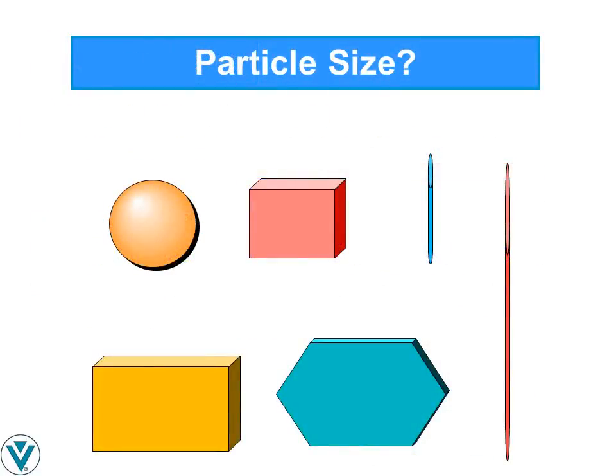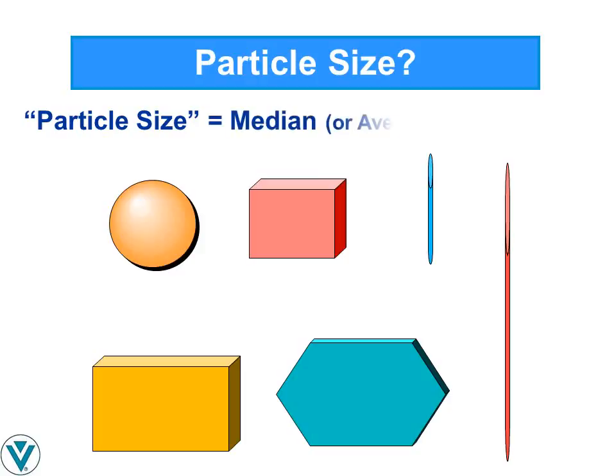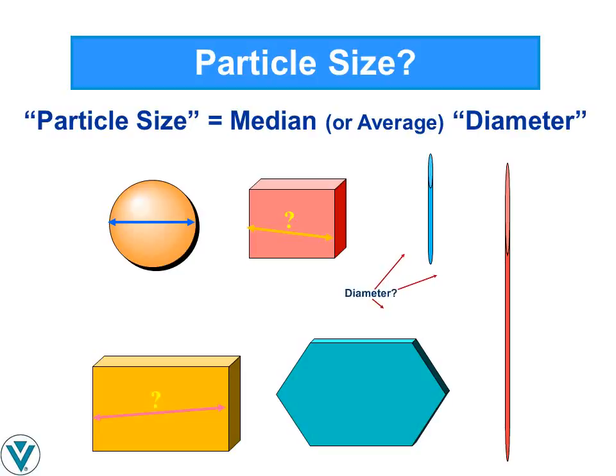There is probably no single property of fillers that is as misleading and misunderstood as particle size. A filler's technical description may contain a value, usually in microns, for median particle size or median diameter. This number is actually of limited practical value. The only three-dimensional geometric shape that can be unequivocally defined by a single number, such as diameter, is a sphere. The diameters of nodular and blocky particles are poorly related to that of a sphere. Platy and acicular minerals, particularly high aspect ratio types, cannot be defined in any literal sense solely by diameter, yet that is the way their particle sizes are routinely characterized.